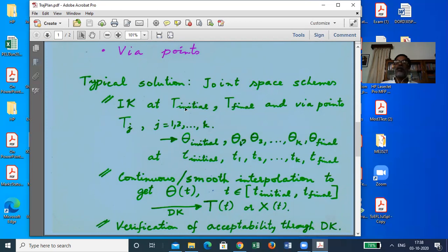Originally the plan was needed at the transformation level, which is the result of all the joints of the manipulator. But now that you have converted it into the joint variables, how different joint values are going to change from this set to this set and this set to the next set doesn't matter.